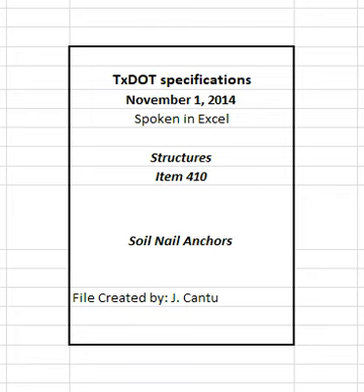Proof testing may occur before the placement of pneumatically placed concrete for the temporary face. Leave a sufficiently voided region around the nail head to allow free nail movement if proof testing is to occur after the placement of pneumatically placed concrete for the temporary facing. Provide a minimum 2 inches clear zone around the grouted nail.